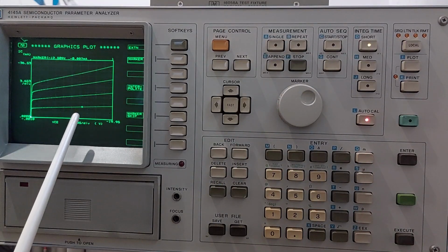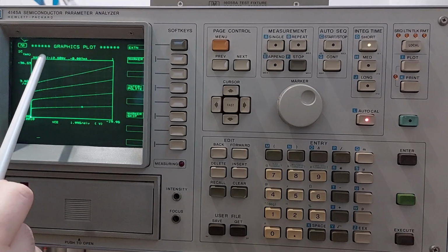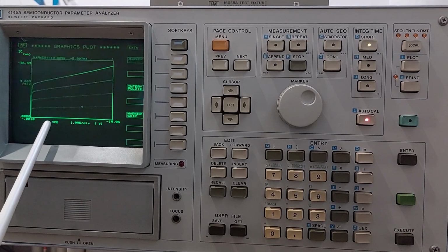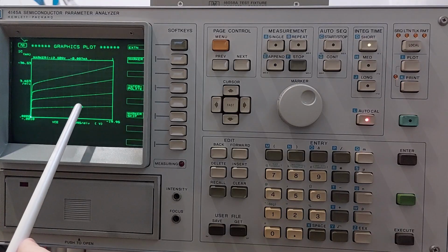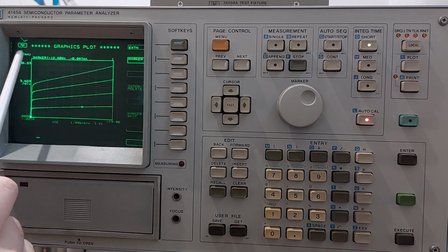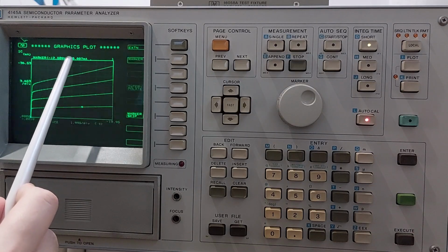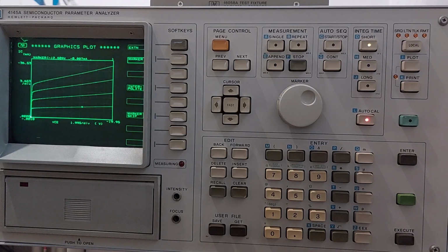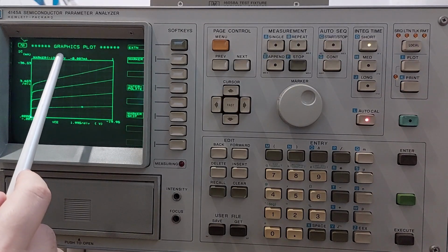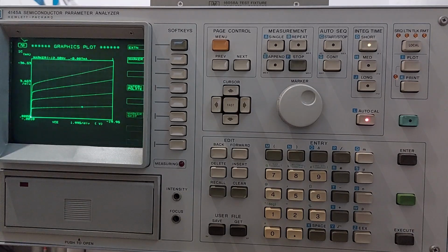So right now we know that for the minus 12 collector emitter voltage and minus 20 microampere base current, the collector current is minus 8 milliampere. So then we just divide minus 8 milliampere by minus 20 microampere, and we will get value of 400. So this 400 is our DC current gain for this transistor, which is well within spec of the datasheet.